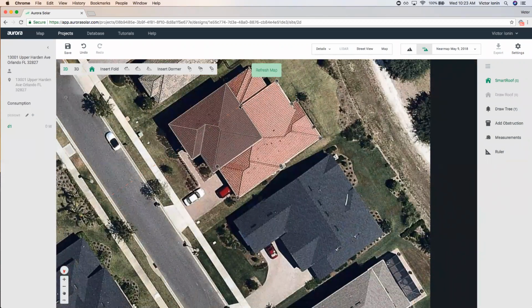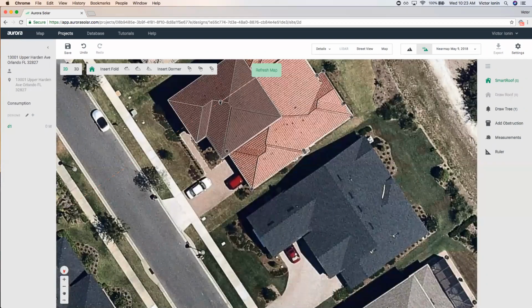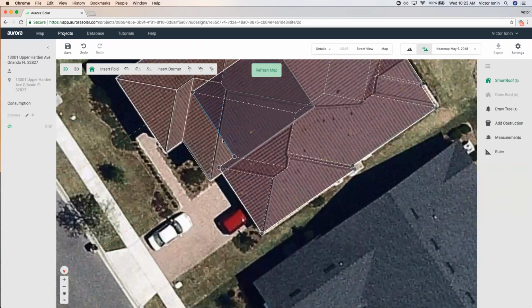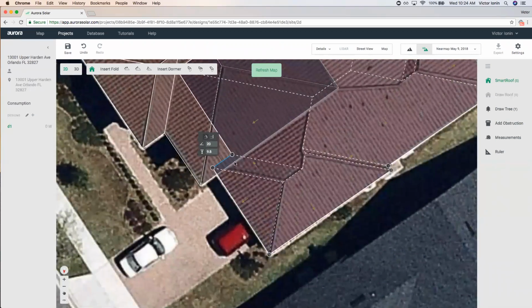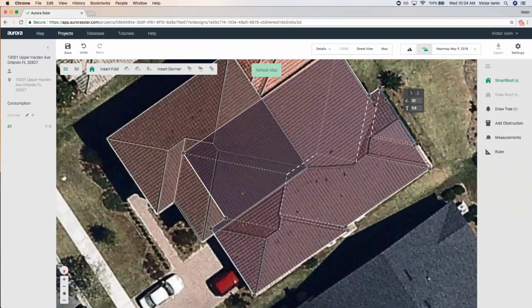We'll go around and I'm tempted to close it off like this because I like to try and keep everything 90 degrees, but I noticed there's also this north face here. So let's just do something like this. There. So I get that north face because I drew in this line here. It looks like everything is lined up. I don't need this triangle piece. I need a ridge that runs across. So let's unpitch. So that looks good.